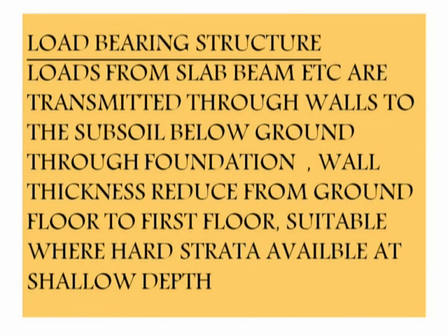This type of the load-bearing structures are suitable where hard strata is available at the shallow depth. When the hard rock or the hard soil is available at the shallow depth, you can have the construction of this type of the load-bearing structure, means that the load is being transmitted to the foundation through the wall.